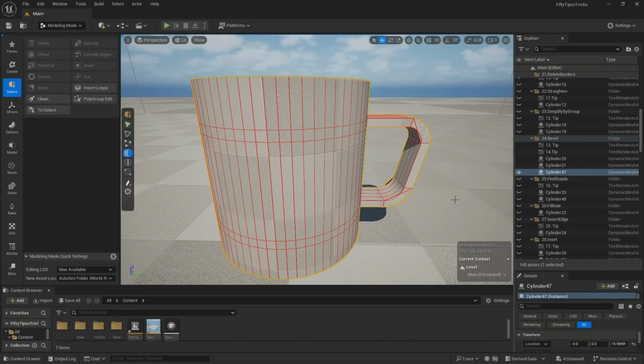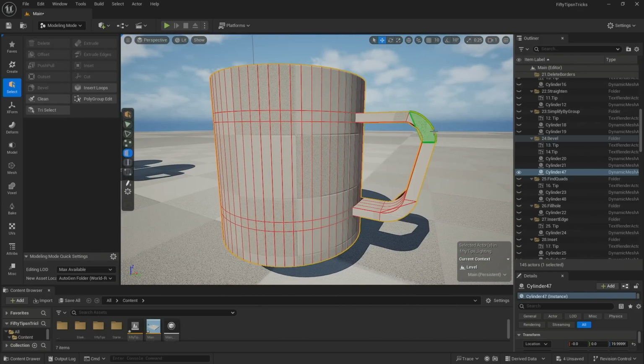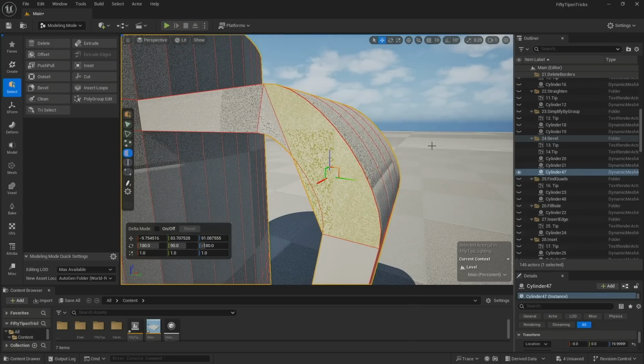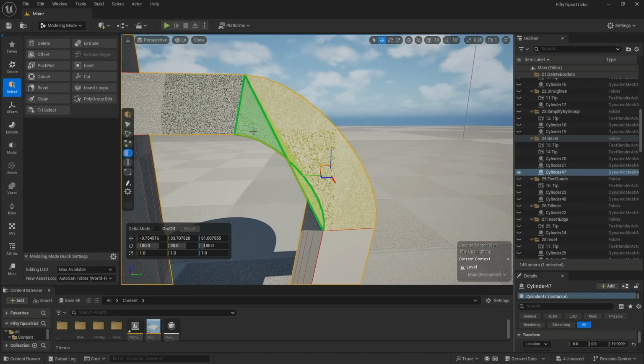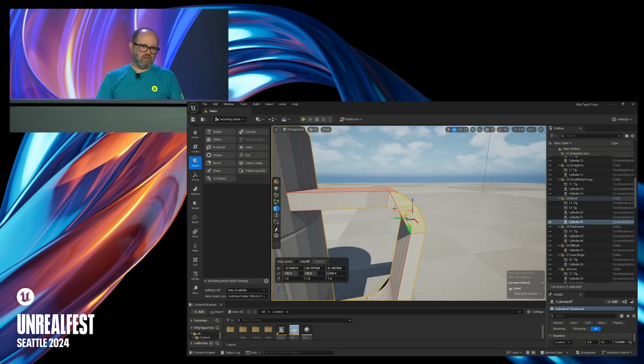So we have these nice edges. Everything looks great. The one thing that you'll notice is these outside faces are not exactly ideal, because of the way the bevel works on this individual shape. This happens in every package where sometimes the bevels overlap over top of each other. In this particular case, I'm just going to go ahead and delete these faces right here.